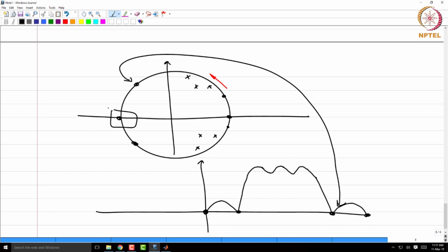So, from the pole-zero plot, given information such as each pole is close enough to cause a bump and the response is equiripple, you can easily come up with this. And there are 6 poles and there are 6 bumps, 3 from 0 to pi, and similarly, so you have 1, 2, 3, 4, 5, 6 poles, 6 bumps.